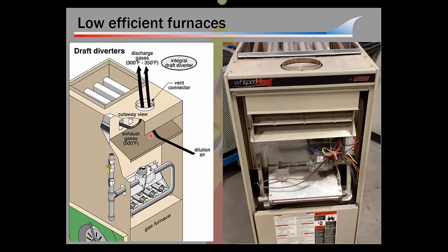So here's how it works. There's burners on here. So there's 4 burners, and sorry I don't have a better view of the burners, but there's 1, 2, 3, 4 burners. Same over here, 1, 2, 3, 4. The exhaust gases come out of each individual burner and mix in the draft hood with the dilution air and then enter the flue. So if I take and put my combustion probe right there where the red pointer is, I now have a diluted sample, do I not? I've got a ton of dilution air in there.